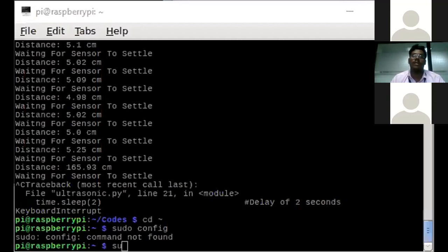Then the SD card reader is one of the SPI communication devices, so we can store data. Whatever data you need to write to a file, you can use it. Then the RFID reader is one of the NFC tags, so it is near field and works 3 to 5 centimeters maximum. It is also one of the SPI communication devices. It is used to connect the sensor with the Raspberry Pi, and we can tag.